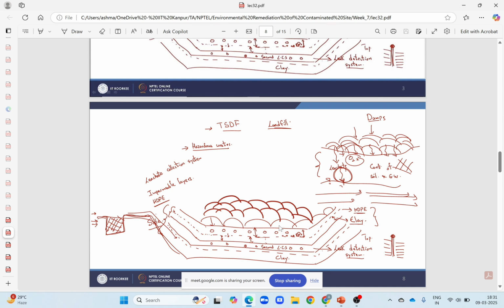So here is an image of the landfill. These black covered areas are the cells. For each day, waste is dumped in a particular size, and that is known as a cell. And at the end of the day, those cells are covered so that animals or other organisms cannot come in contact with that.